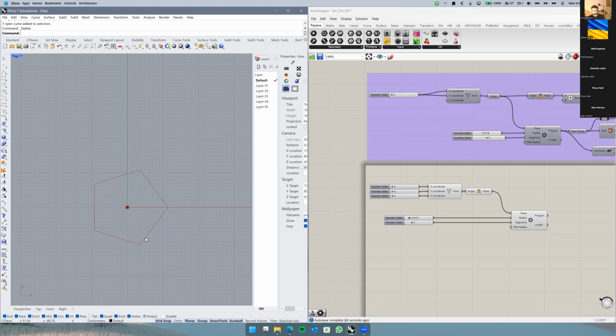I would pick the object Plane first. Then I would either select the line, select a point, a corner, something that I can take as a reference, and I would drag it over to the point that I want to place it on. So that's what we are going to do actually. I want to take this point here in the middle of this line, this edge, and move it here. So I know how much I need to move. That's my distance. And then I know where this point is. This is just in the middle of this line.